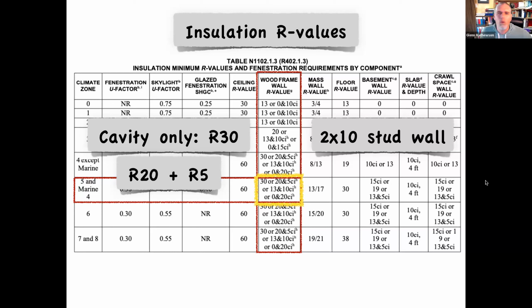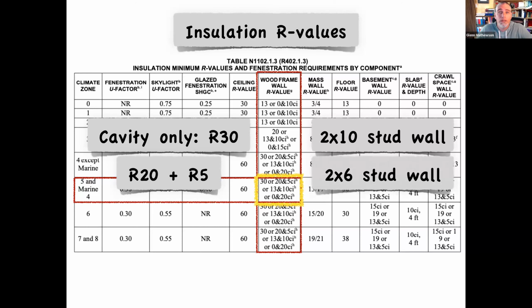But what is R20? Why did we pick R20? Why does the recipe use that? Well, because that's common ingredients available on the market. That's what common insulation manufacturers produce. Why, Glenn? Why do they produce R20? Well, because it fits in the common studs that are out there in the market. So much of code is developed around what we already have, around, I hate to say baggage, but things that we really don't have a lot we can do with.